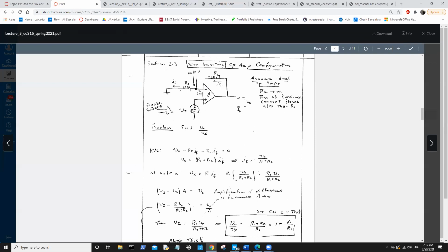So the voltage source is down here, and this is a ground sink. So our negative feedback, because yet again, look, it says this is still a virtual ground node. Nothing comes into this terminal. That's why it's a virtual ground node. So the IF that comes out from the V out just goes right over R1 through node X and goes to ground. So these are the same. So you solve for this side, and you're done. Because then you'll have a way to represent the relationship between R1, R2, IF with V out. And VI somewhere else, I'm sure, probably.